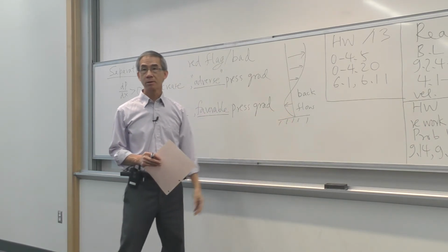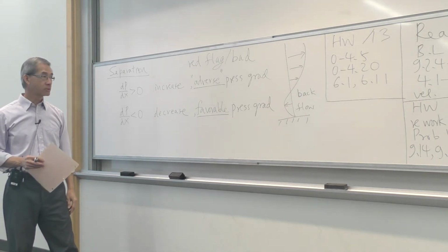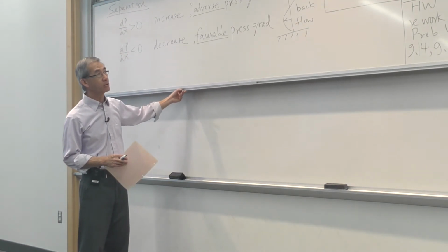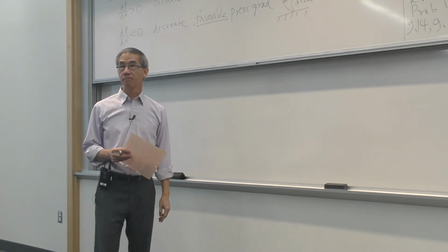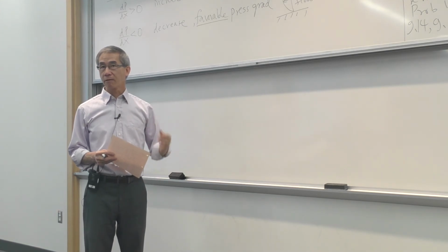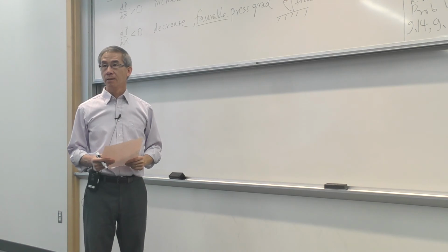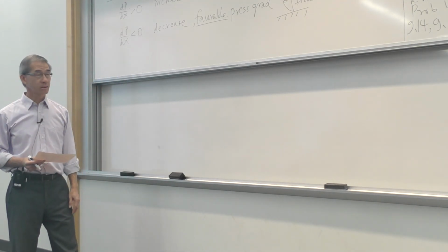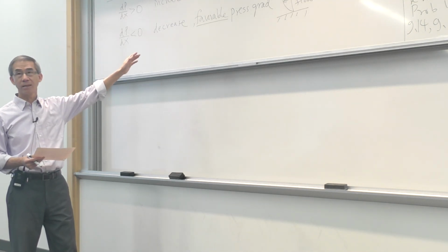And that separation causes an airplane to plummet, losing lift, because the boundary layer just peels off completely on the suction side, or the upper side, of that airfoil, and all hell breaks loose. This is bad for a lot of phenomena, like an airplane stall, an aircraft engine stall, a complete breakdown in the diffuser. Saying the boundary layer separated, all of a sudden the blockage becomes much more, and the intent of the design of that engine device